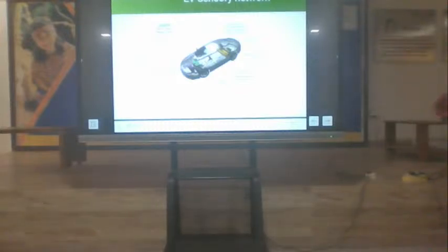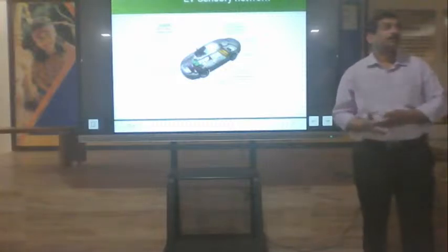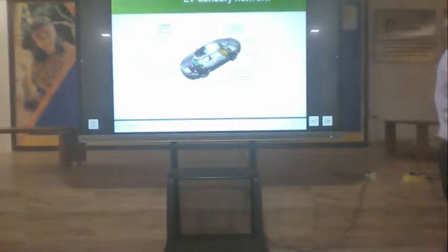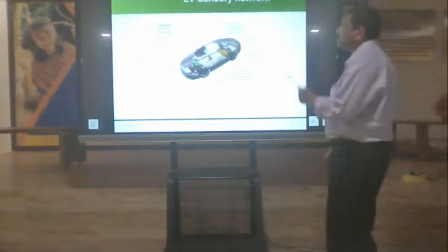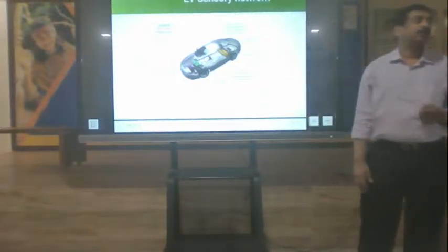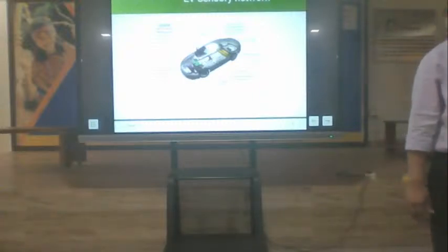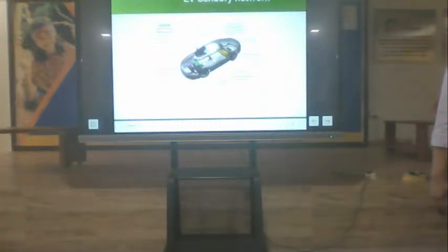All that sensor network is digital devices working on a low voltage. So the high voltage is converted into low voltage by multiple DC-DC converters. And mind you, in your electric EV, it is mandatory that every converter within it should have an efficiency above 95%. So imagine what technology they would have put in to have those minimum losses.